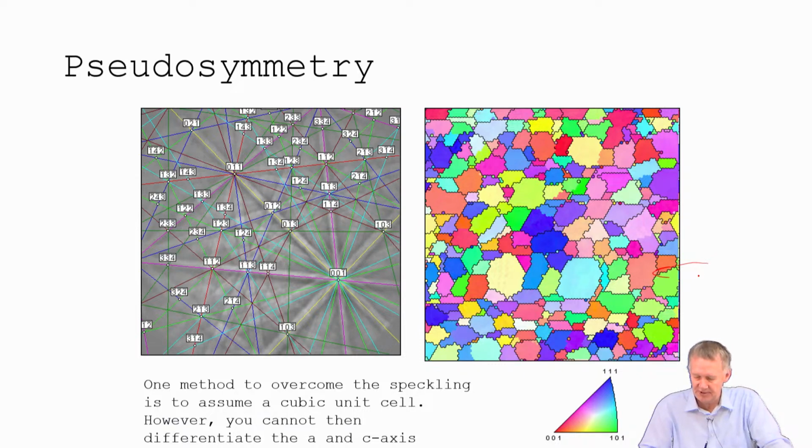So one of those methods would be if there's a mechanical property difference between C and A axis, which happens really nicely in the superconducting material, the YBCO material I was telling you about, the yttrium-based superconductor. If you do nano indents inside where you did the EBSD scans, then you can determine very nicely if that was an A or a C axis.